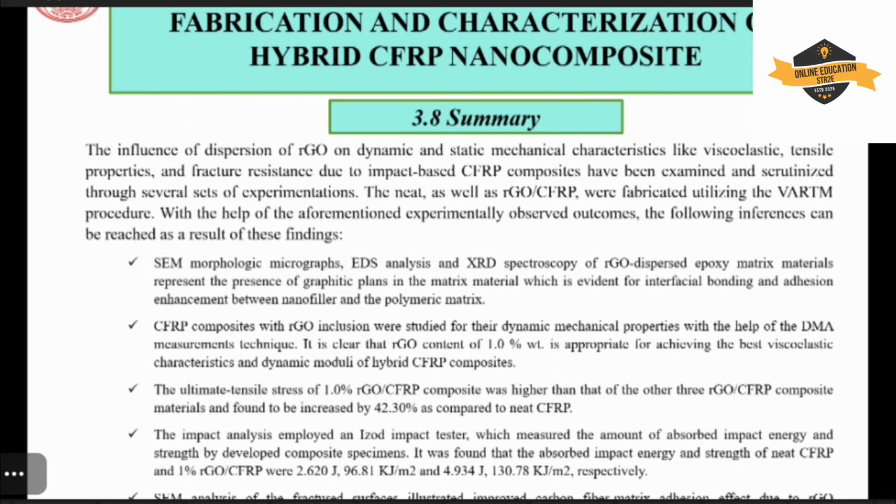Here, for the efficient synthesis process, we have used the vacuum assisted resin transfer molding process, and other conventional processes are also there, but the most important and significant point of study in vacuum assisted resin transfer molding is the different types of manufacturing defects, such as blow holes and air entrapped during the manufacturing process.